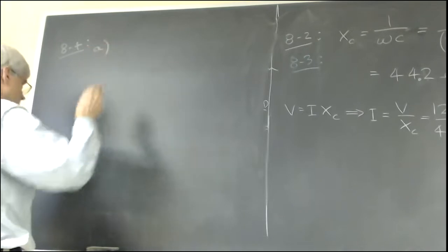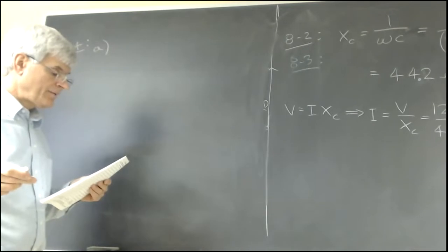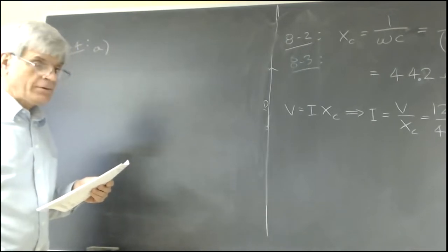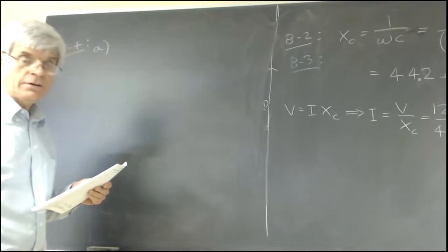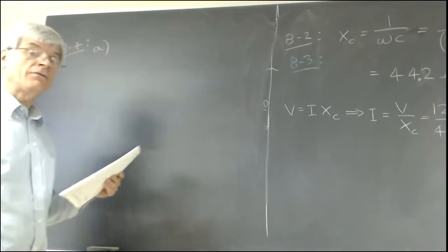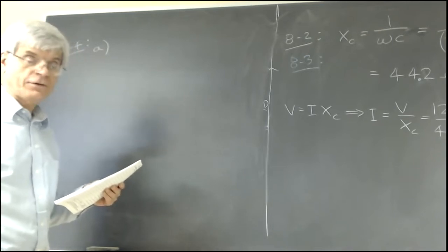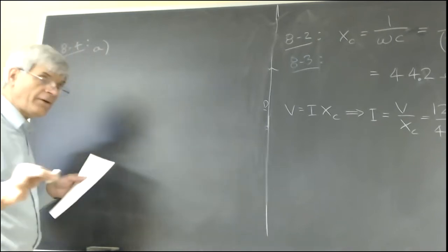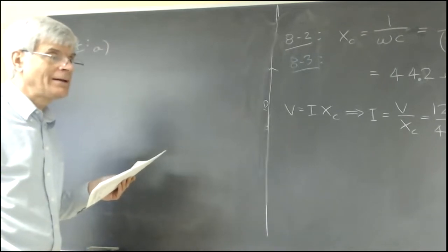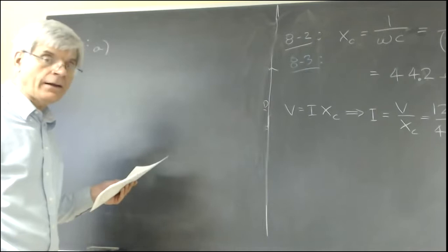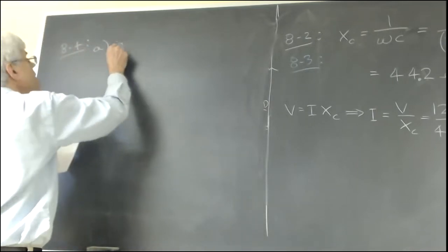Part A. If you have 250 ohms at a certain frequency, you've got 250 ohms at every other frequency. Resistance is not a function of frequency. There are other factors that can affect resistance, like the temperature of the resistor, but assuming you don't overheat the thing, still 250 ohms.